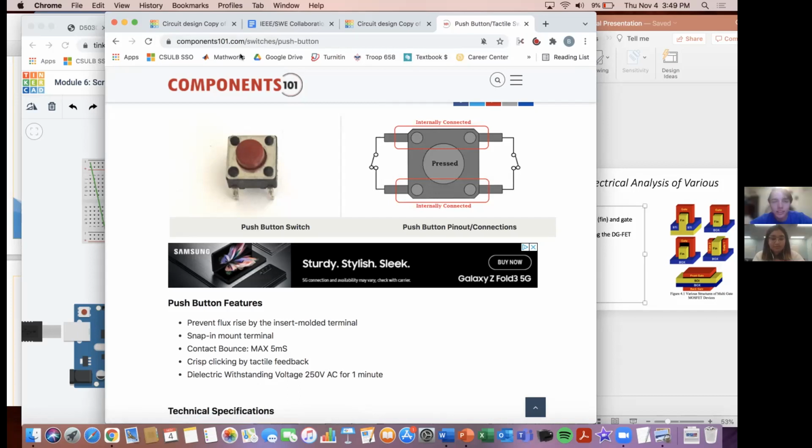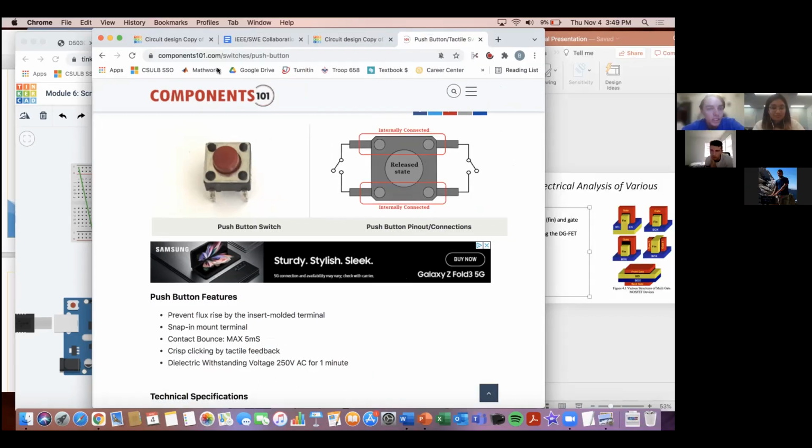I do have one other question. Do people ever connect Arduinos to something other than a breadboard? I connected mine to a fan. That was for my final project because I could do pulse width modulation on it. It could send out a signal to the fan to go faster or slower, so it could determine the fan's speed. That's what I used it for one time.